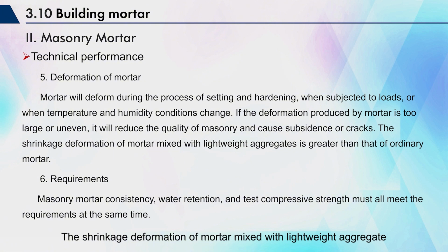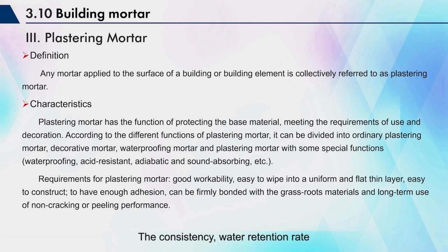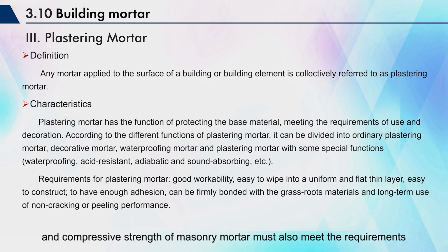The shrinkage deformation of mortar mixed with lightweight aggregate is greater than that of ordinary mortar. The consistency, water retention rate, and compressive strength of masonry mortar must also meet the requirements.